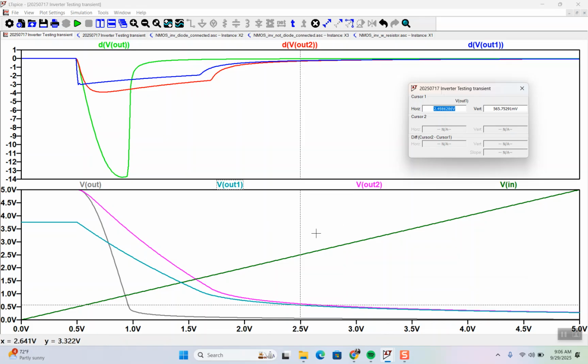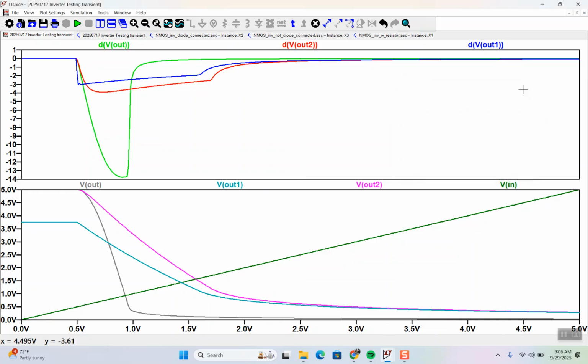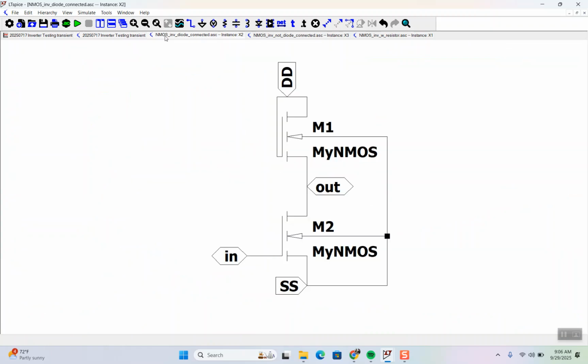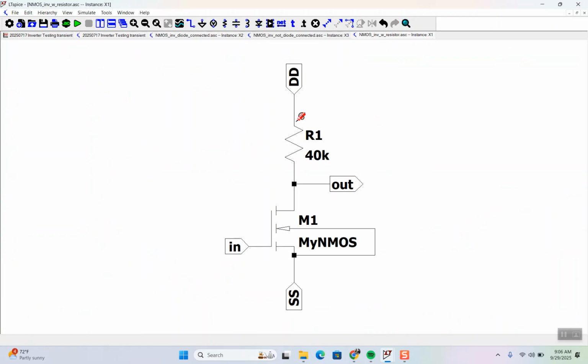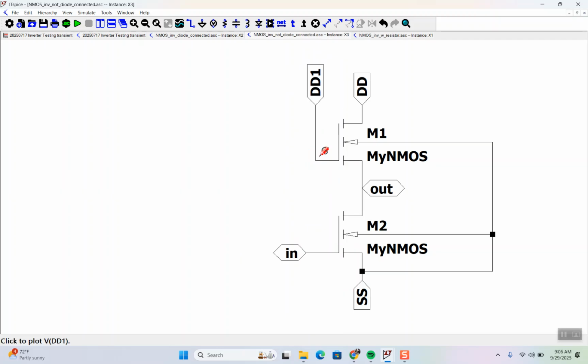And as a quick aside, you can use that for analog with a whole lot of work, right? But you've got to get these output highs and lows first. And so notice we have purple and we have the gray. I'll come back here and tell you what those are. So the resistively loaded one, when this transistor is off, there's no current flow, no voltage drop, and V out equals VDD. Great. But the linear one, oh no, let me come to here.